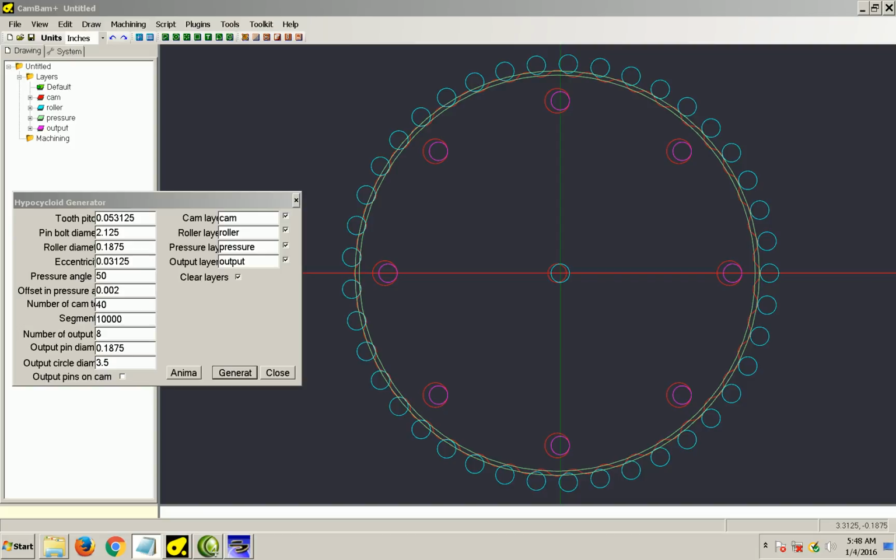There were two choices for making the housing: machine the housing with pins as an integral feature, or drill and ream holes, then use dowel pins. I tried both, and the dowel pin method proved to be far superior, due to the fact that they have a more accurate geometry, smoother surface finish, and are harder.